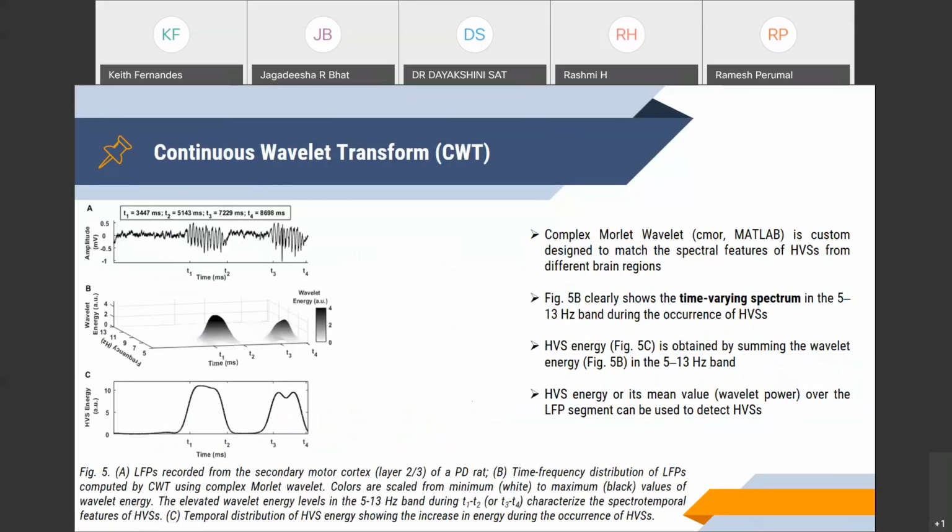The next solution is that we need time information and frequency information at each time instant. So we can go for the continuous wavelet transform. By using the continuous wavelet transform, we can compute the time-frequency distribution that shows the features of the signal in the time-frequency plane. That is very efficient and very helpful to analyze the signal offline. We will see the algorithm here.